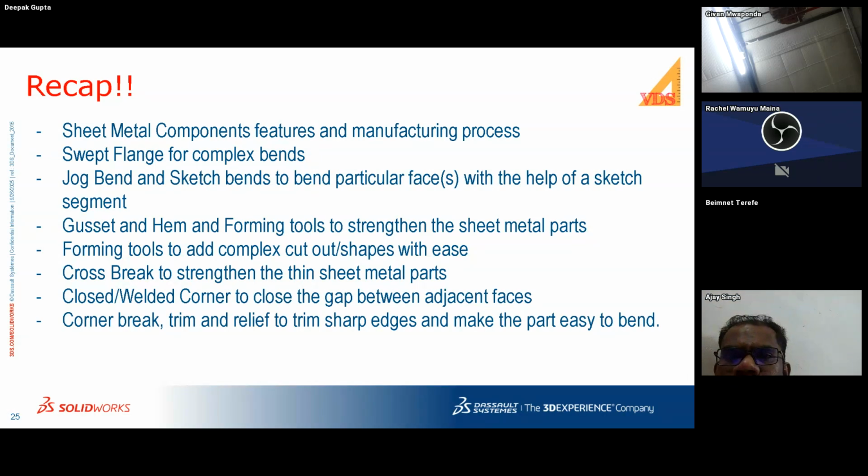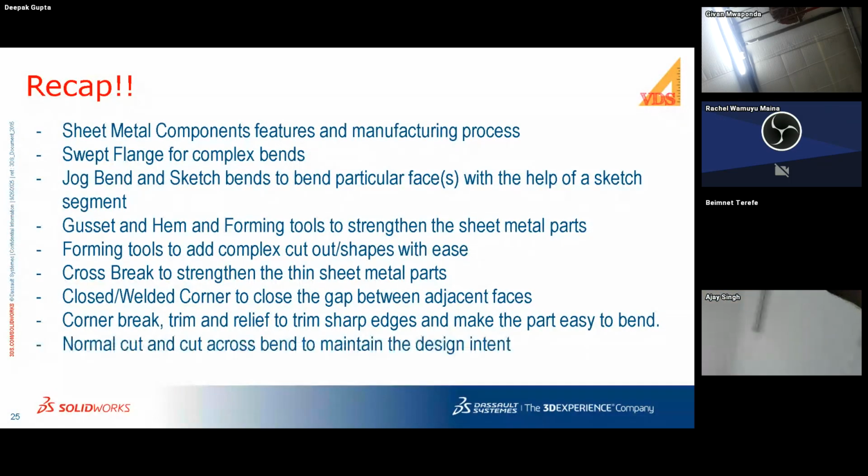We looked at different corner treatments as well, which helped us remove the sharp edges and also provide reliefs around the bendage around the corners to smoothen out the bends and make them easier in manufacturing. And we looked at the normal cut and cut across the bend.